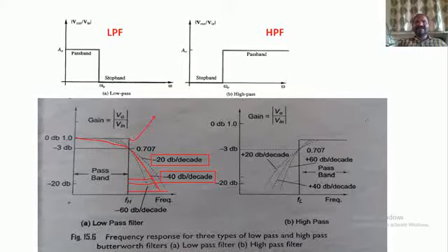They are not giving the ideal values. As they are not acting as ideal elements, obviously we are not going to get this sharp response, but we can reduce the number of frequency components which are accepted by the filter after the cutoff frequency by increasing the order. So we are increasing up to the third order. If you increase to the third order, then the reduction is a little faster. So this is the third order response. In this case, only a few components are going to be accepted by the filter, compared to the first order and second order; only fewer frequency components are accepted after the cutoff frequency.